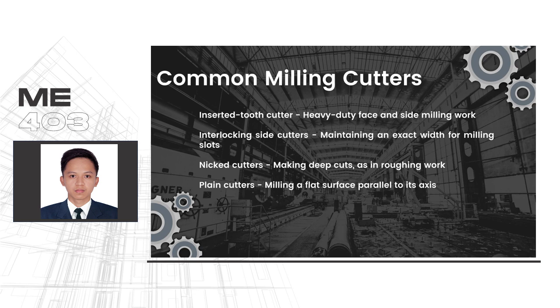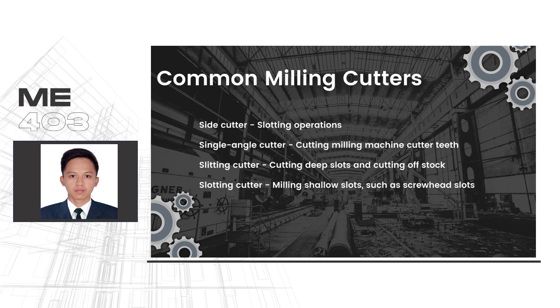Interlocking side cutters, designed to maintain an exact width for milling slots. Nicked cutters, suited for making deep cuts as in roughing work. Plane cutters, used to mill a flat surface parallel to its axis. Side cutter, suitable for slotting operations.